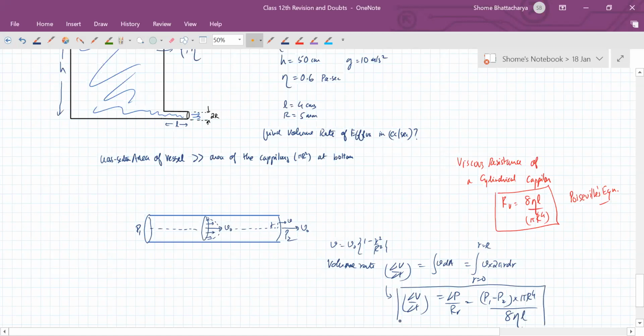So in this case, we don't have to worry about the above formula, these ones which I'm writing. Just have to understand the values here. So what is happening here is, this point and this point are the ends of the pipe, and liquid is coming out through this with that laminar flow. So this we will replace with PA minus PB, which will be rho GH.